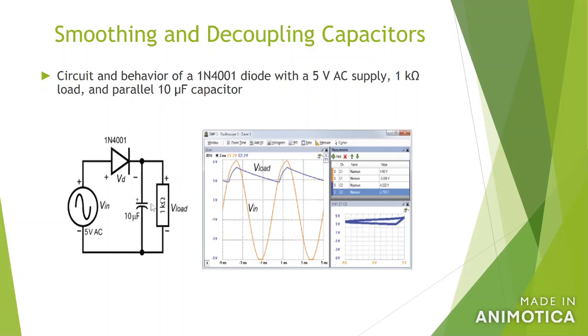So a capacitor is a kind of device that can be charged. Basically, when the current flows through the diode, the capacitor is charged during that period. Then when the current flows back, it will be blocked by the diode.